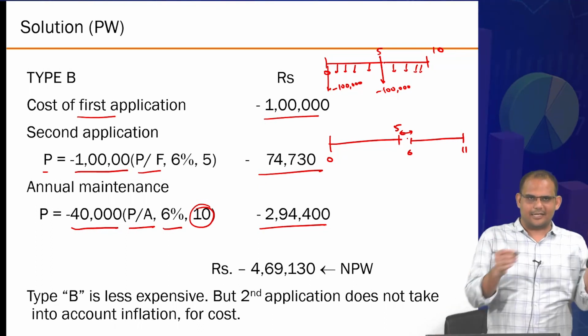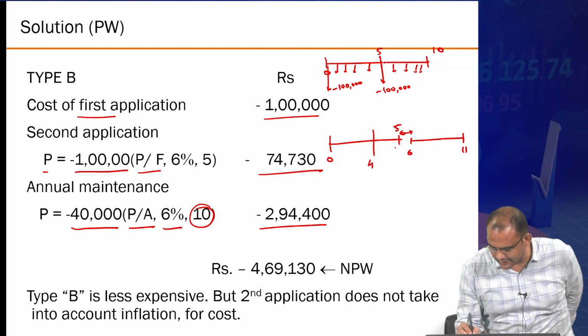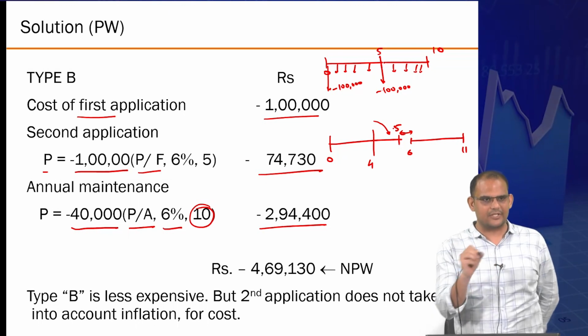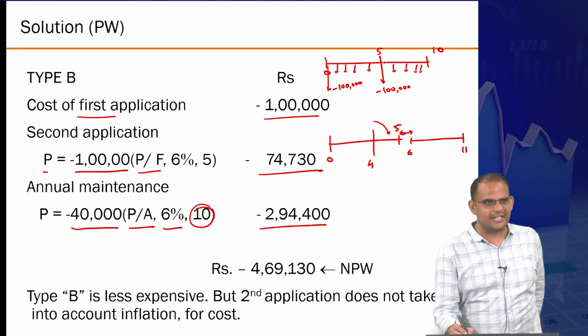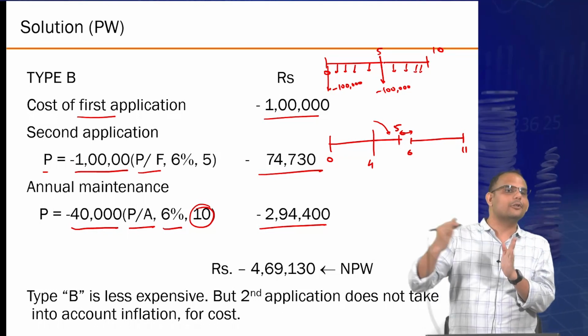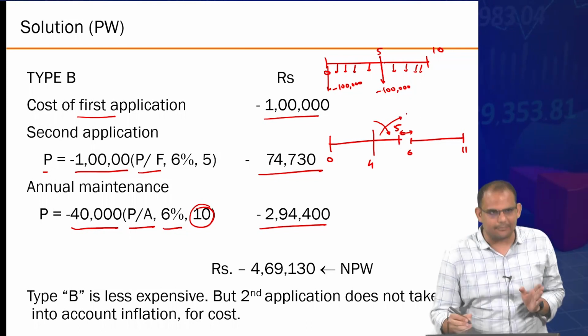So the idea is that maybe your road is already between the year 4 and 5, your road is already on the downward trend, performance of it is already on the downward trend, such that at the end of year 5 it will become 0. If you want to continue the operations, you need to start putting money to keep it on the same level.